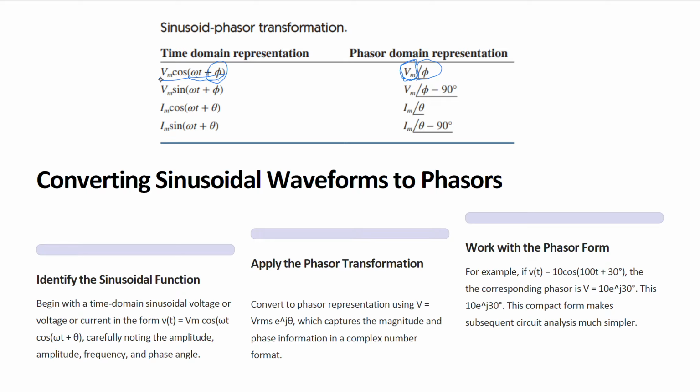Why? Because Vmax has an alternation regarding the omega. How can we get rid of that? Same as I talked about the root mean square, because root mean square will basically eliminate the time variation. So we can accurately represent the phasor of this cosine by the RMS voltage and the initial phase angle, which is whatever is inside the cosine at time 0.